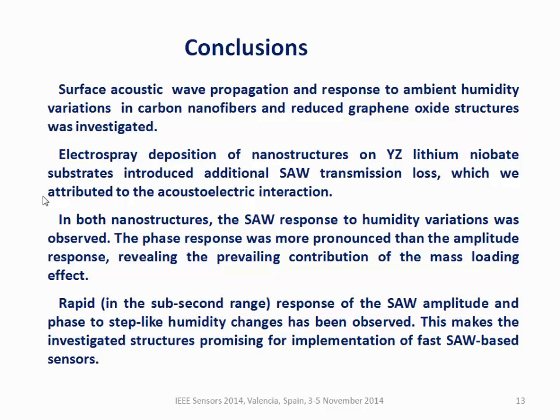In both nanostructures, a response to humidity variation was observed. The phase response was more pronounced than the amplitude response, revealing the prevailing contribution of the mass loading effect. Rapid, sub-second response of the amplitude and phase to step-like humidity changes has been observed. This makes the investigated structures promising for implementation of fast SAW-based sensors.